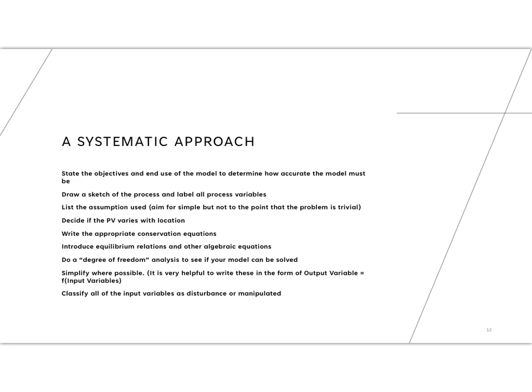Maybe it's the flow rate in, maybe it's a changing pressure in, and try and decide whether or not you think this is something that is a disturbance that you have no control over, or maybe someone has control over it. Someone opened a valve and now you have a whole lot of extra flow. But you didn't do that. So that would be a disturbance. Or maybe it's a change in the weather that caused an upheaval to the temperature. Okay. So those are disturbances.